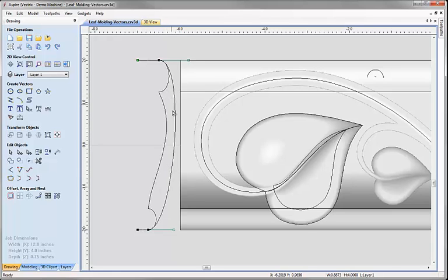Now I can see if we use that shape, that's going to add an awful lot of thickness to my design. So what I want to do is add some other points in here. Let me click I on the keyboard to insert a point and drag this down so that it's just slightly above the point here. Then we'll just move that around there.